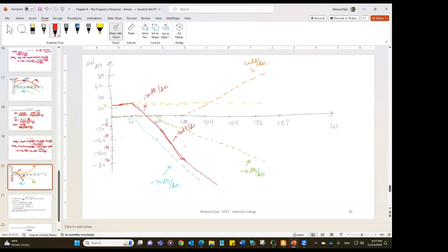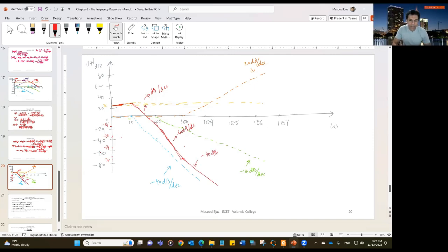Is there a point on the Bode plot where it's just too small a value to account for? Well, these are all decibels. So as it is going down, your signal is being attenuated a lot. So you can plot it based on what is the highest frequency in yours. For example, our highest frequency was 1000. So you can just plot it up to 10,000. That should be okay, whatever the value coming out at that point.